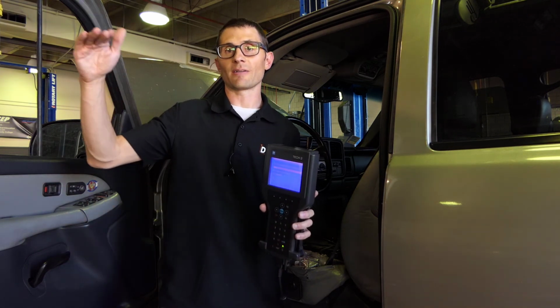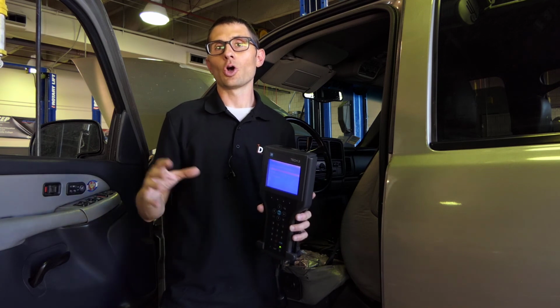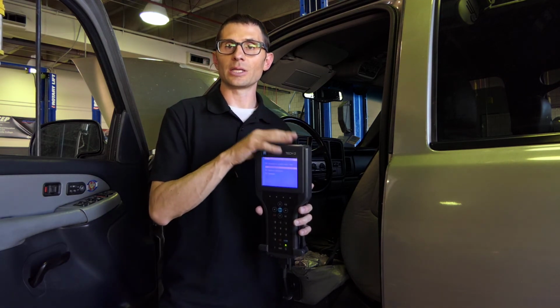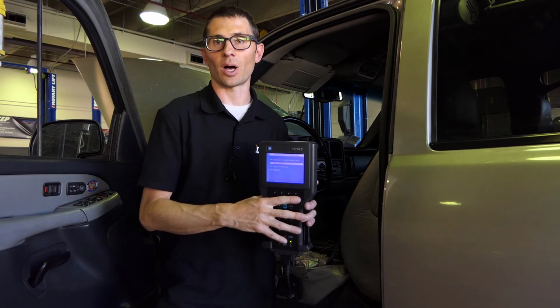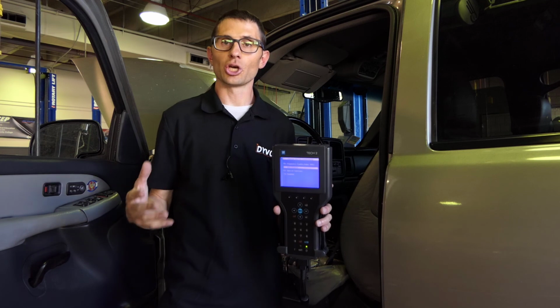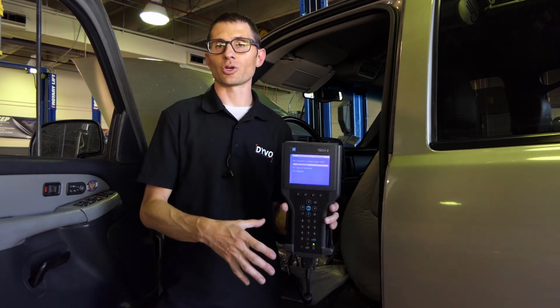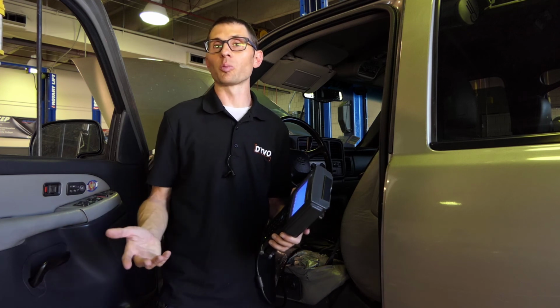circuit down and it was sitting at 5 volts, we entered the load mode and we pulled that circuit down. We could have actually gone into the Tech 2, gone into the special functions and updated the HVAC module to see that change immediately. And by seeing that change, you would have then known that the wires in the circuitry as well as the control module were all functioning as they should. That's probably a good way to do it.